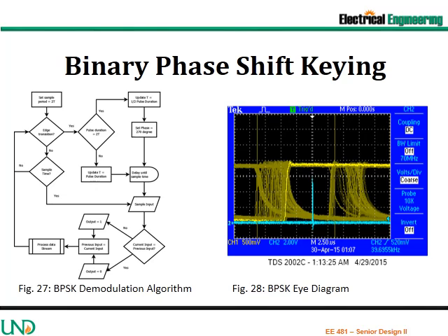The algorithm utilizes 8 synchronizer bits. This is not a performance algorithm, but it is robust and can synchronize mid-data stream. 5 microseconds of jitter margin are shown at the selected data rate. Differential encoding results in a 1-bit delay. However, this allows for phase inversion when aligned to either the positive or negative detector.